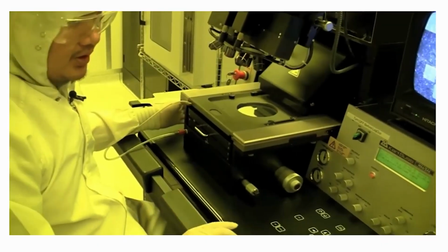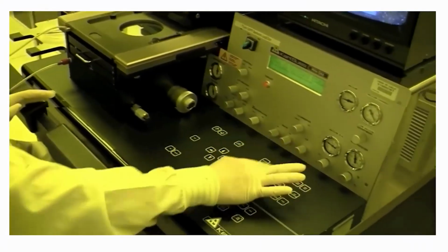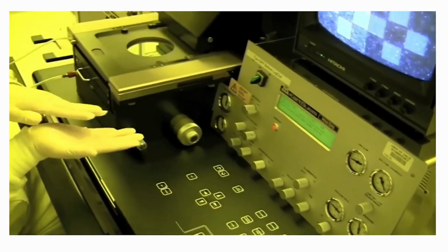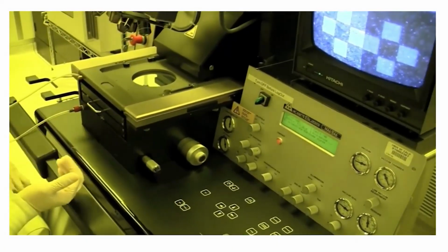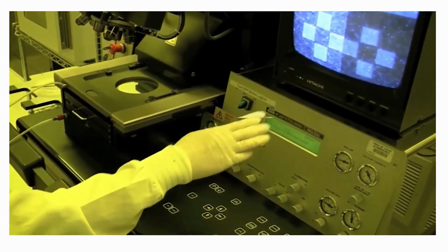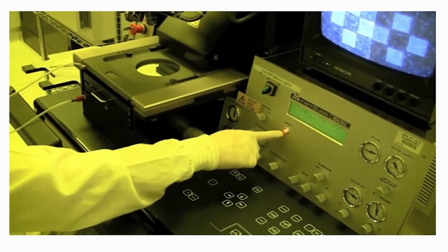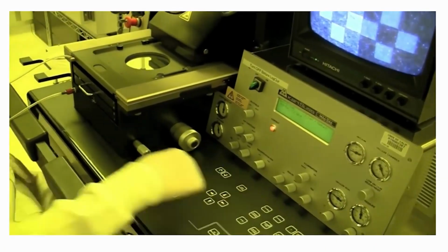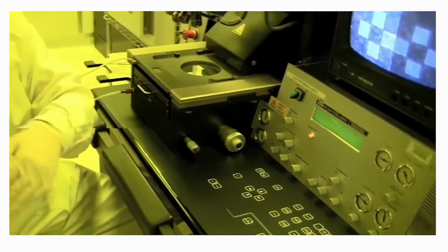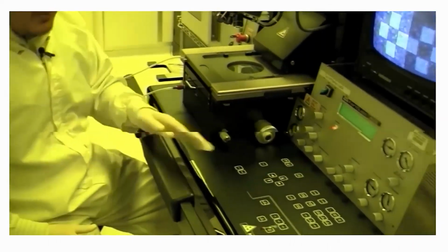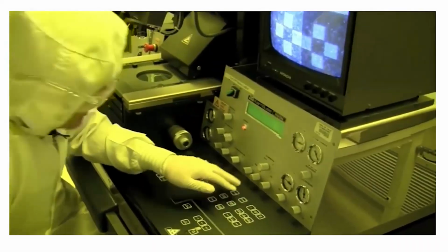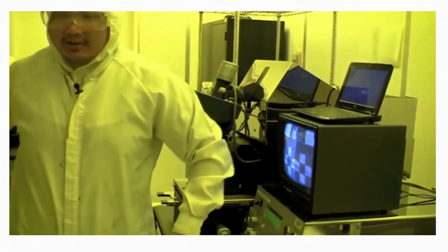And how do you expose? You press the first do alignment check, which will bring it up to touch. You want to make sure nothing moved. And then when it's in contact, you hit exposure. And when you hit exposure, it's good to turn your back away from the light so it doesn't damage your eye. So we hit exposure, and then we just turn away.